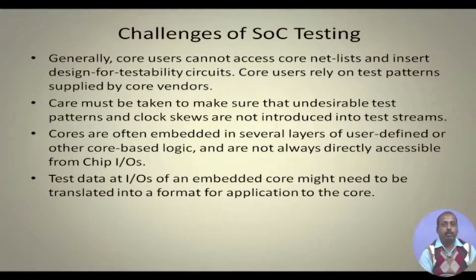So, that is available with the core vendor, which is never told to the system integrator, because the intellectual right is protected there. So, the users of the core, that is the system integrator, do not have access to the netlist, and they cannot insert design for testability circuits into it.